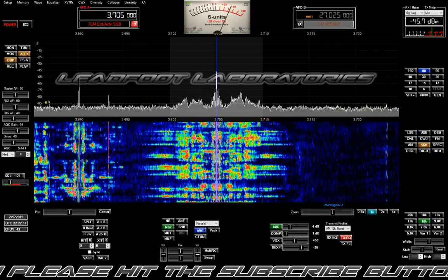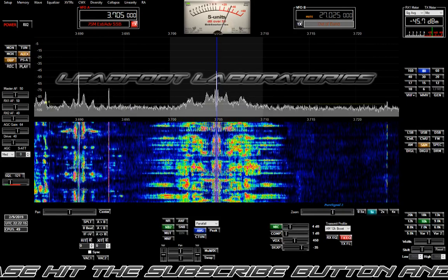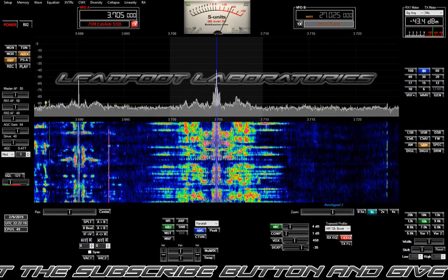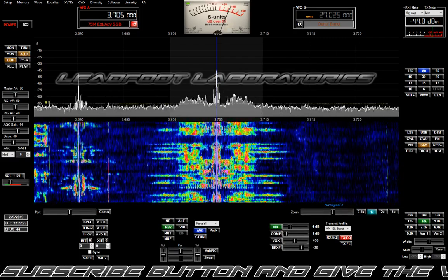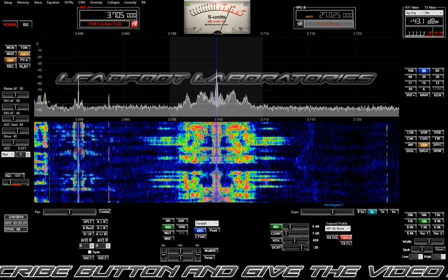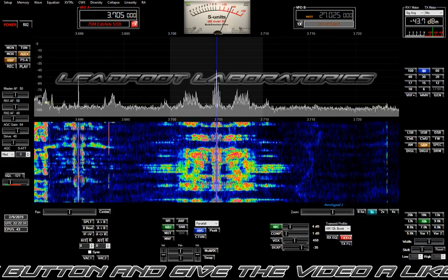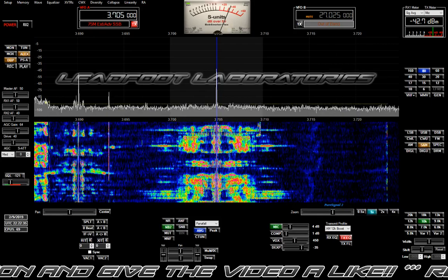and then obviously it compensates to create a best fit straight line, and that's the linearization that takes place. And I've heard that using pre-distortion, you can see third-order distortion products, third-order IMD, on the order of like minus 50 dBc, which is amazing. I mean, there was a time when maybe 35 dBc was considered spectacular for an amateur radio amplifier. Grounded grid. But 50 dBc to get a 15 dB improvement, that's phenomenal.